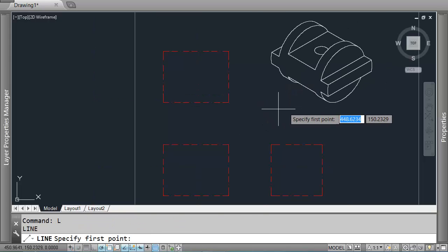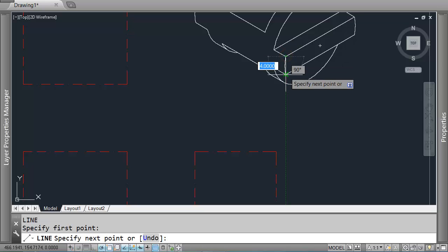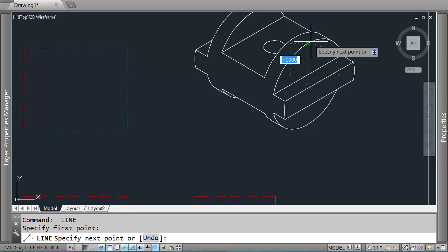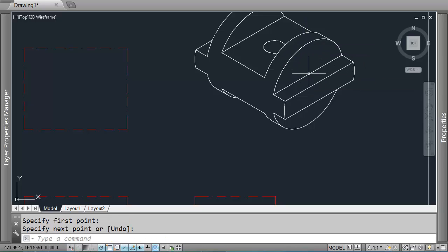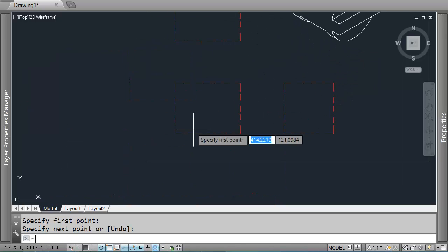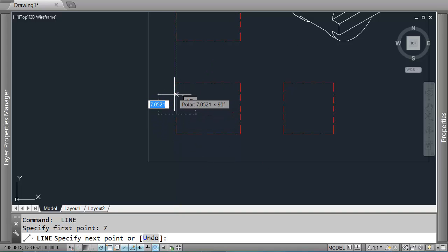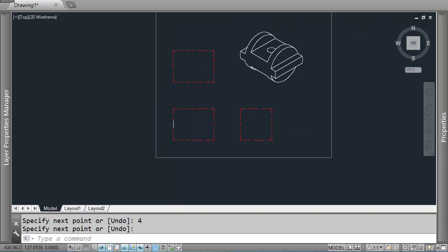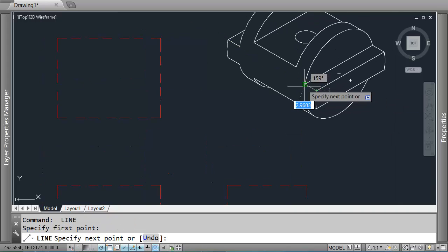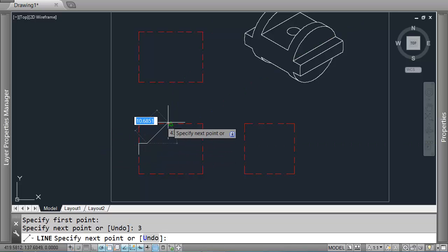So what do we see first? I suppose starting from the middle of the shape, we would see this 4-unit high end piece. We can know that 4-unit high part is going to be 7 units off of the bottom or top of the face. So I'm going to come up 7. I'm then going to come up 4 here. What do we have next? We're going to go across slightly. This is a distance of 3 units across.